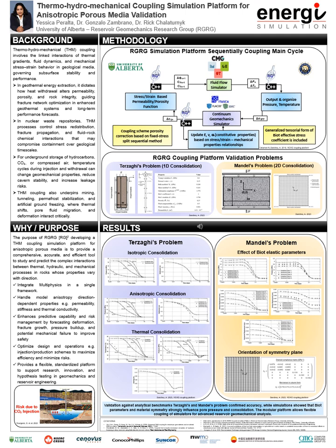The third case for this benchmark is thermal consolidation. We included thermal effects. A heater at the top raised the temperature by 50 degrees, inducing thermal stresses, pore pressure increase, and surface heaving.